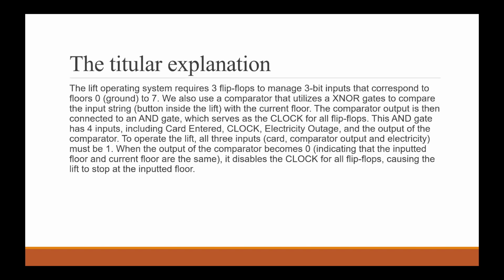This AND gate has four inputs, including card entered, clock, electricity outage, and the output of the comparator. To operate the lift, card, comparator output, and electricity must all be 1. When the output of the comparator becomes 0, indicating that the input floor and the current floor are the same, it disables the clock for all flip-flops, causing the lift to stop at the input floor.